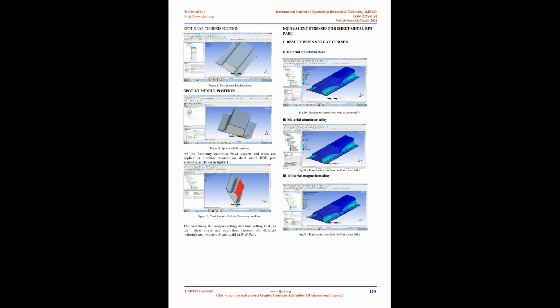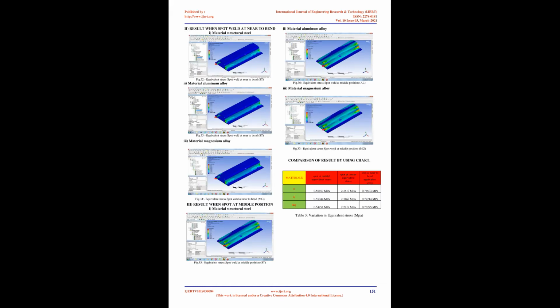Electrodes convey a pressing force to the joint and direct the welding current to the joint in the appropriate manner. After welding, the electrodes rapidly cool down the welded joint. Work stages in resistance welding are very fast. The surfaces to be welded do not usually need to be cleaned before welding, in addition to which the weld does not usually require grinding or post-heating. The resistance welding process can be easily automated. Resistance welding is a highly efficient production method that is particularly well suited for automated production lines and mass production.